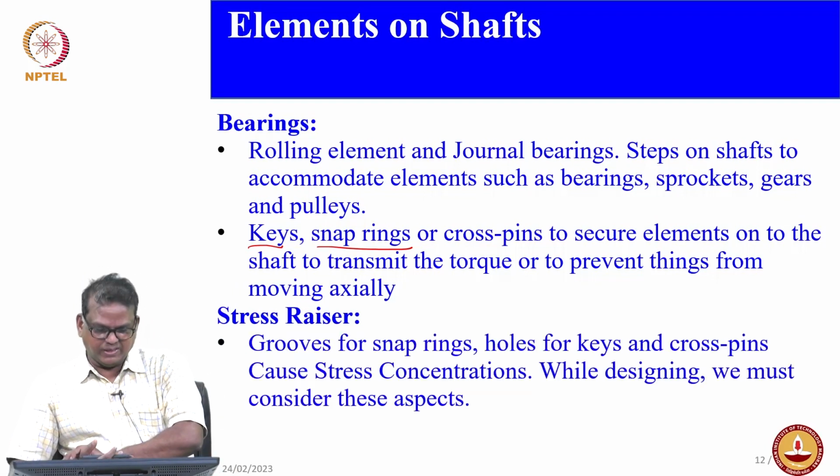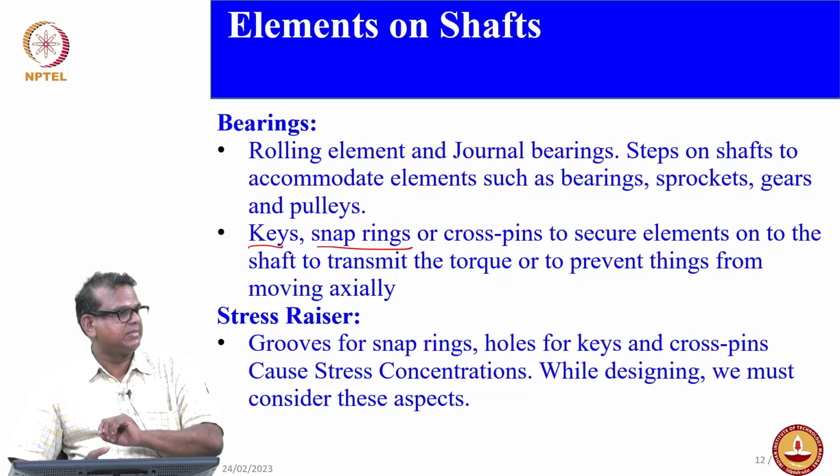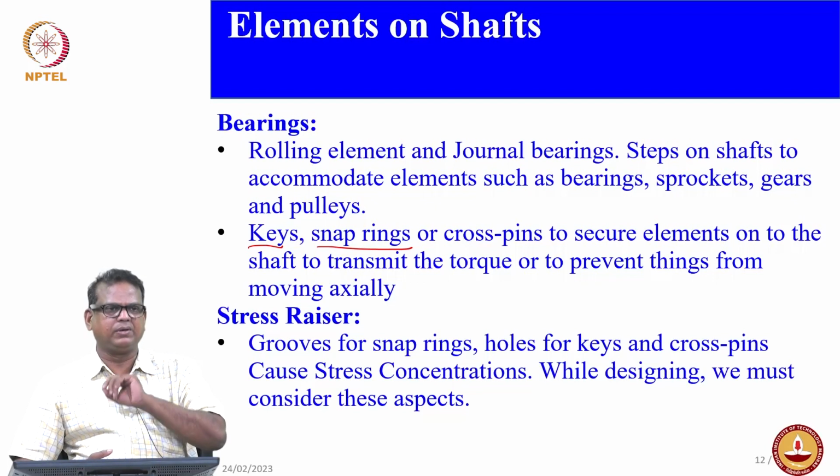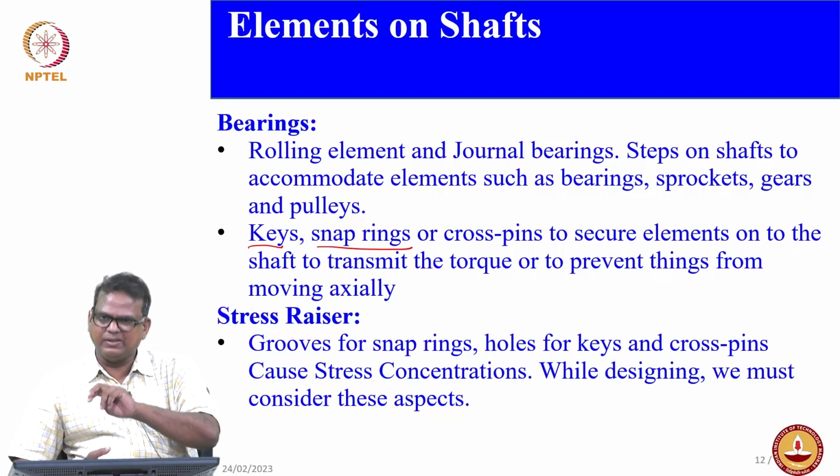Grooves for snap rings, holes for keys and cross pins cause stress concentration. So while designing, we must consider this aspect, the stress concentration factor. I am sure you would have studied in your undergraduate course Ks, Kf, Kfm, right, those factors will come into the picture.